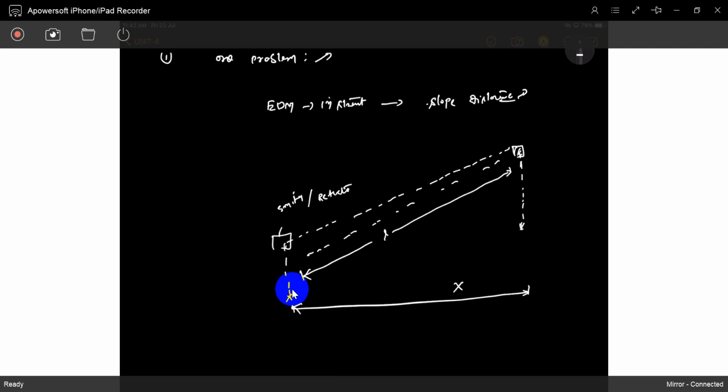You can't get it. So how can we get it, sir? So simple. We already know it. Once you get the slope distance L, if you measure the horizontal angle with respect to the total station, you will get the horizontal distance. Compulsorily we have to use horizontal and vertical angles to find the horizontal distance, not the slope distance. Slope distance only you can get with EDM measurements, not a perpendicular distance. Understood? Not a straight distance or same plane distance.